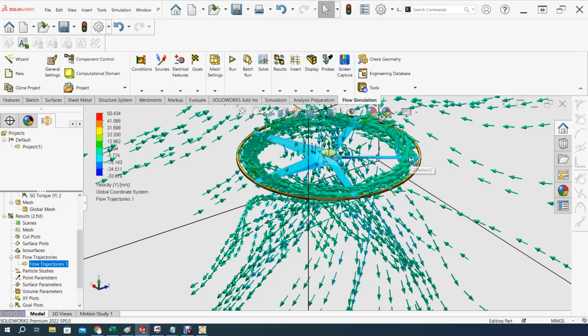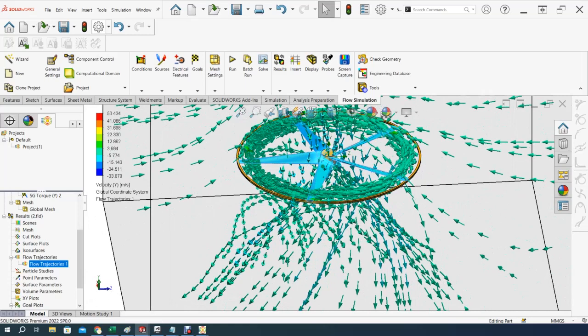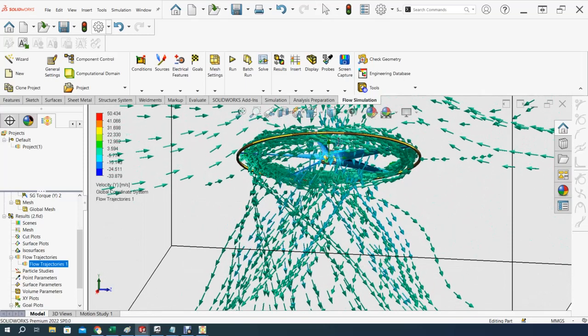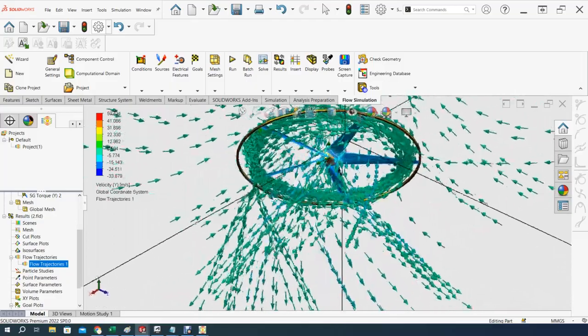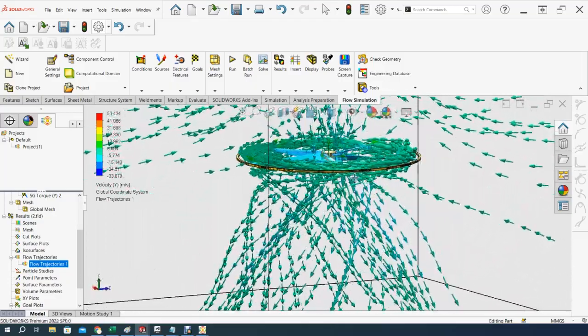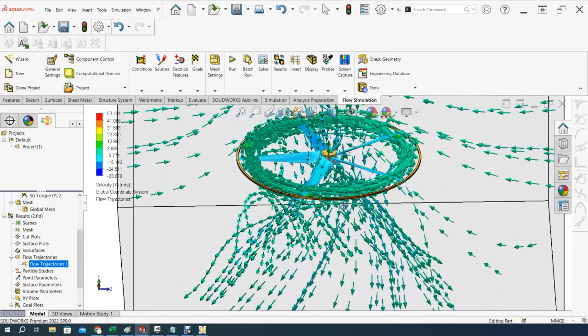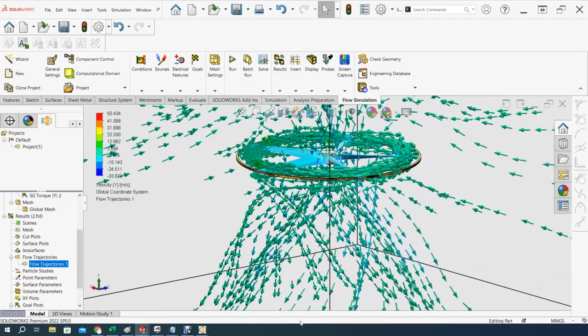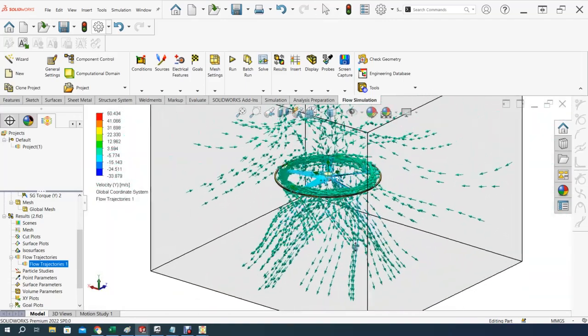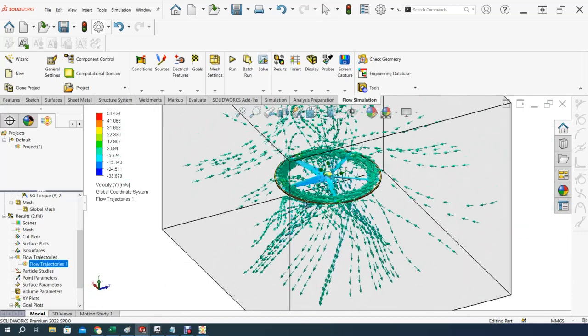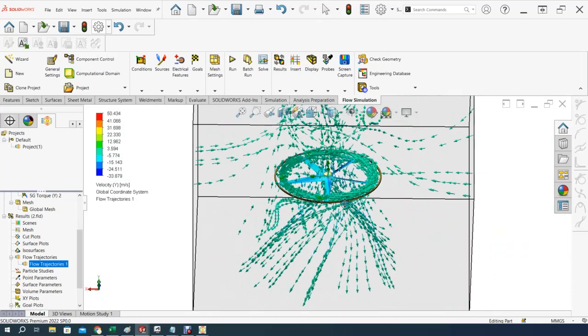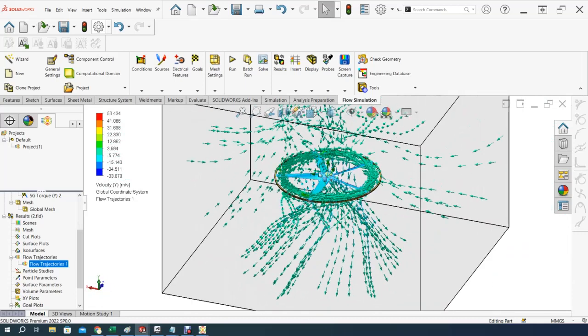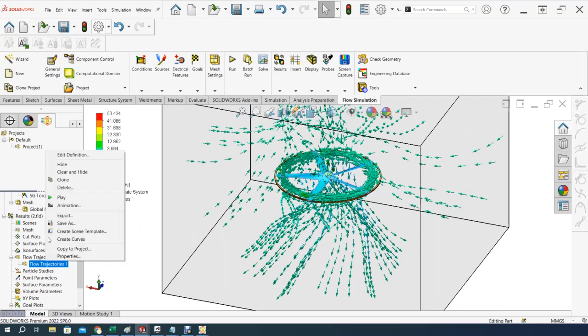Here at the root it's about 35, here at the end is 0. I need more, because basically what I'm doing is circulating air and not pushing the air down, as you can see here. That's not good, and that's at about 5,000. So that's a lot of waste of energy, circulating air and not pushing it down. So you can see with this analysis what needs to be fixed, for unit testing, if you are into the design of propellers. So let's see, play.